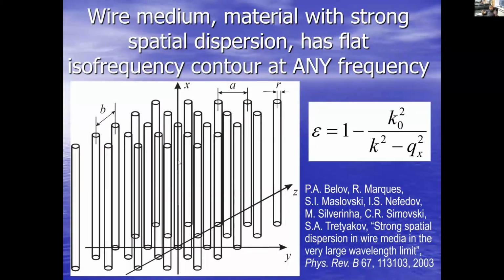We know that just a pair of wires at any distance between them is a very good waveguide. We've chosen this as the first sub-wavelength waveguide in order to create a material. And the material for sub-wavelength imaging is a so-called wire medium. It's just a parallel array of wires. It's densely packed wires parallel to each other, usually with the same radii, usually in periodical arrangements.